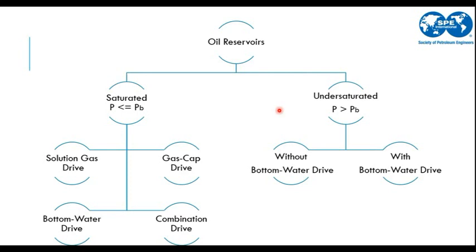The second category, as we said, is the saturated oil reservoirs, where the pressure is less than or equal to the bubble point pressure. So we would see some free gas, but if the free gas isn't enough to form a gas cap, this is called solution gas drive or depletion reservoirs, or gas in solution drive reservoirs.